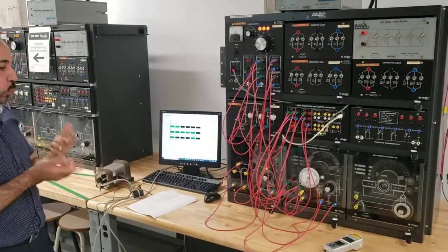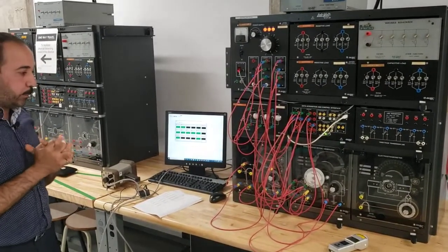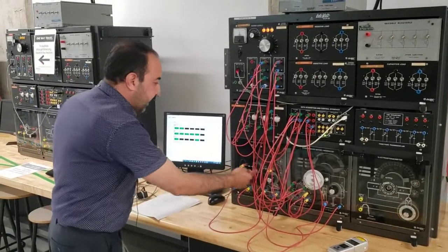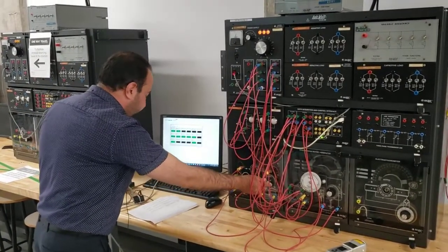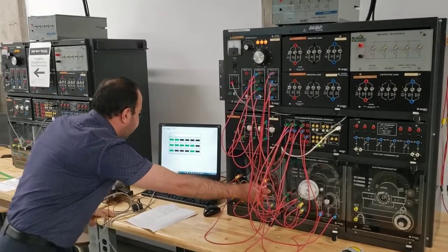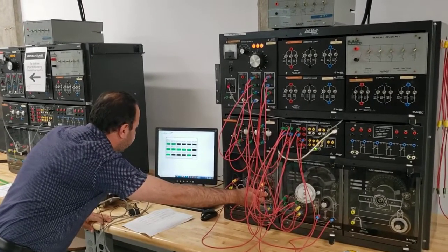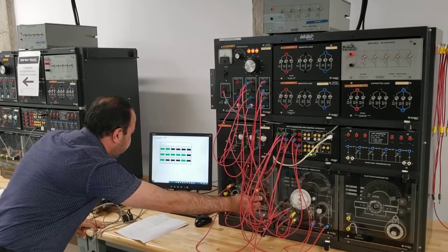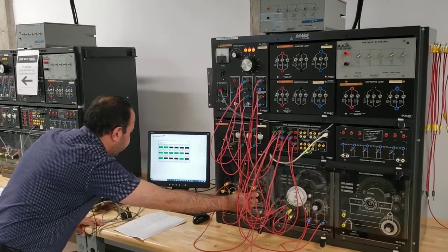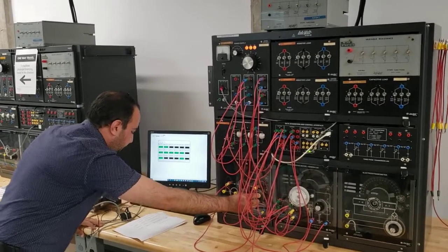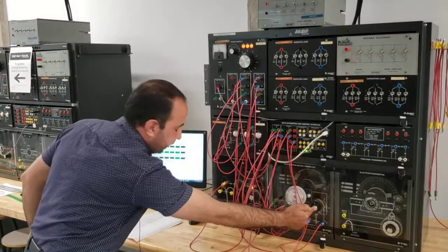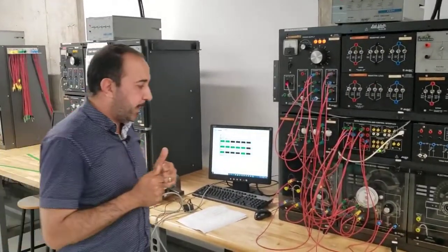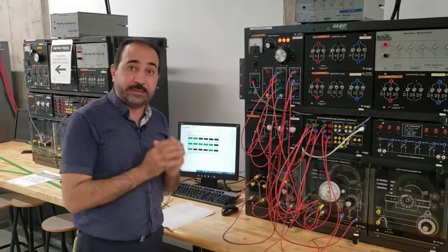Then I would like to work again for constant power. So I would like to make this current 1 ampere and 2 ampere for two different cases. So I will change this current to be 2 ampere. And then I'm going to change the excitation, and I will try to measure IA and P and Q. But don't forget, I would like to measure delta as well.